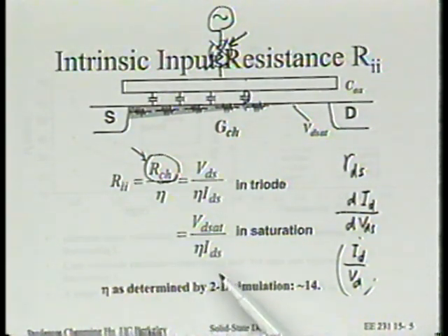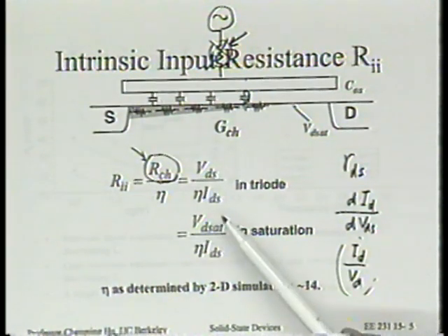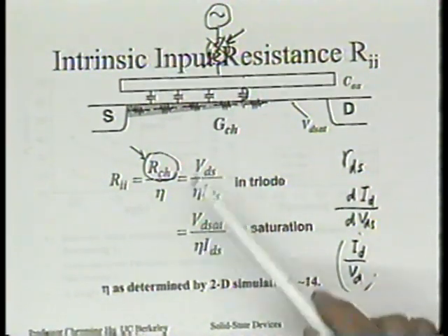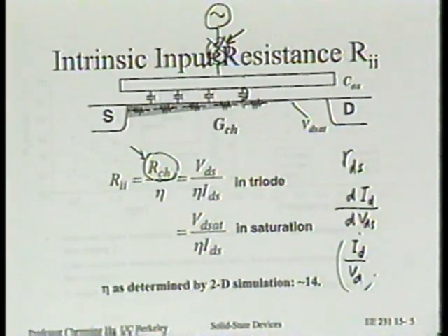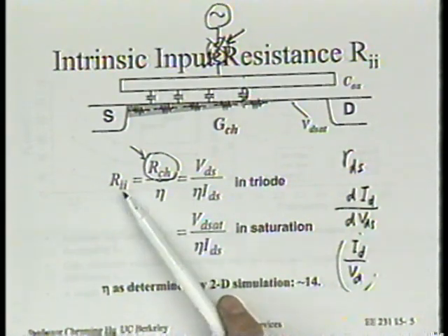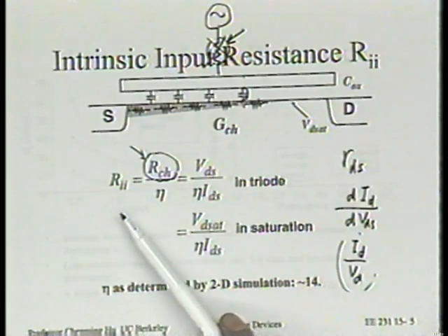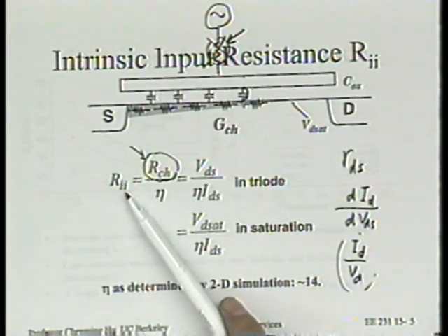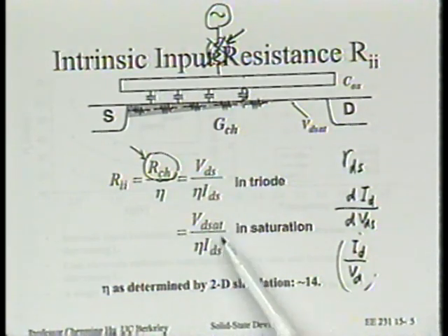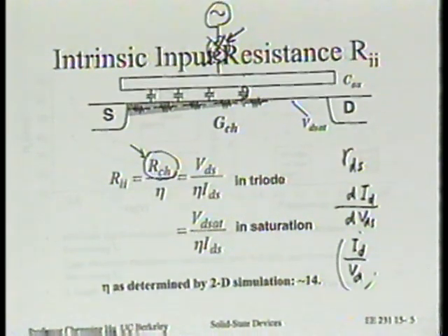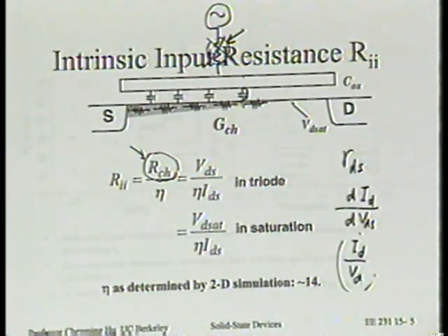This makes the whole model totally continuous because IDS is a continuous function in SPICE already. So we take advantage of that, and don't try to express this in terms of Cox, L, W, and mobility. If you do that, you necessarily introduce a lot of approximations. Don't do that. Just take advantage of what we already have in SPICE. So the mobility doesn't come in. We just directly take the ID.